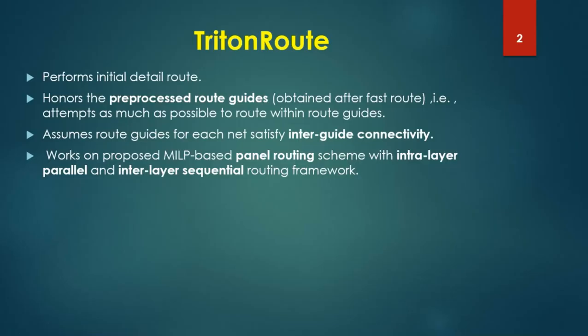And say, for example, there is a connectivity between M1 and M2. So when there is a connectivity between two different layers, you know there has to be a via, whatever you call it. So via placement won't happen when M1 routing is taking place. That means via routing won't happen when the lower layer routing is taking place.